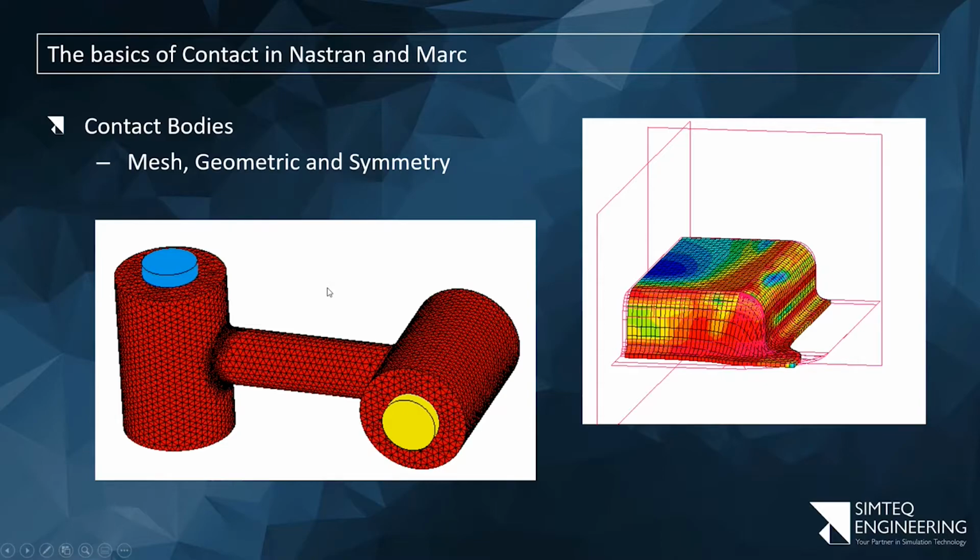Okay, now in terms of contact bodies, this is an example, just a meshed part. It looks like there's only one contact body, and this is how they've selected it, I agree. But the only purpose of a contact body from a mesh perspective is to find which elements participate in that possible contact. What the algorithm will do is say all of these elements are selected.